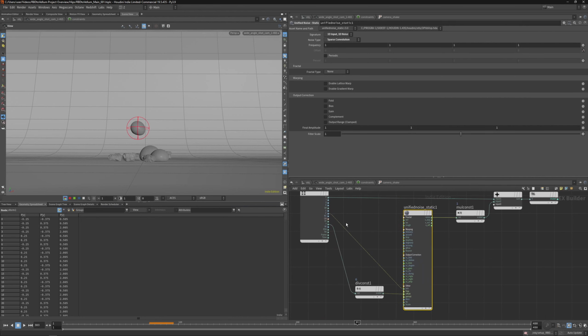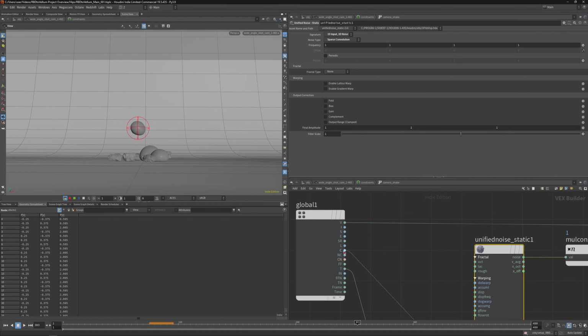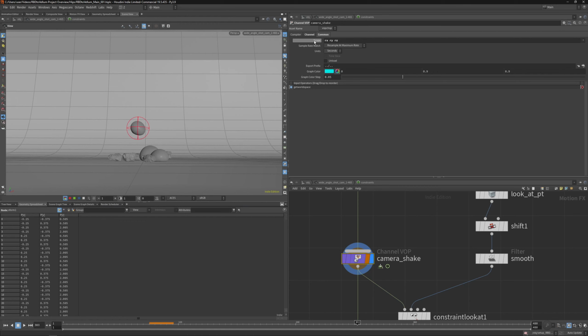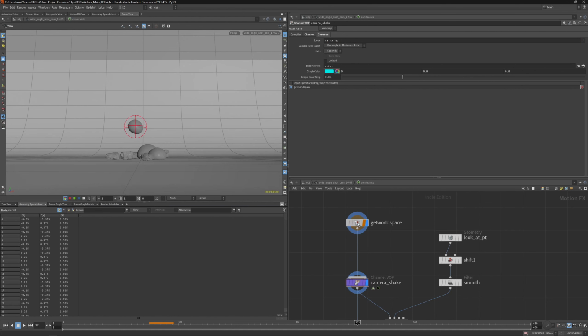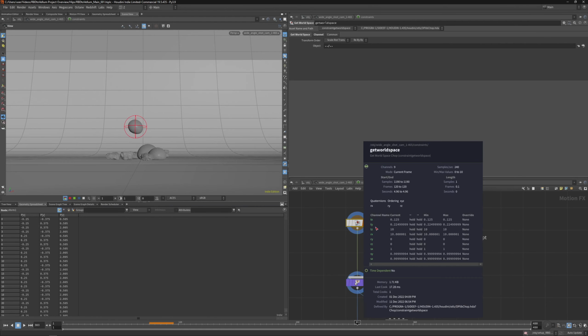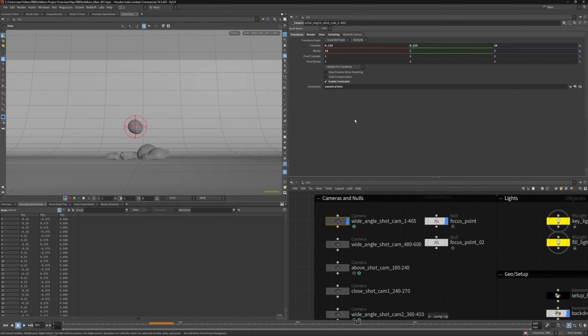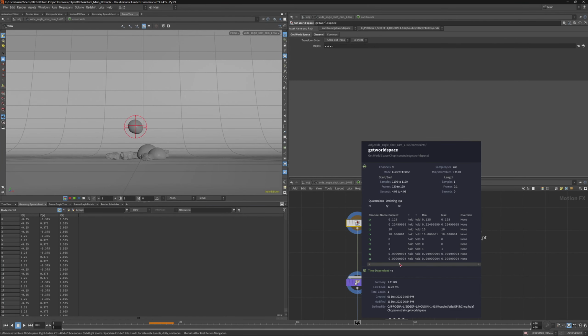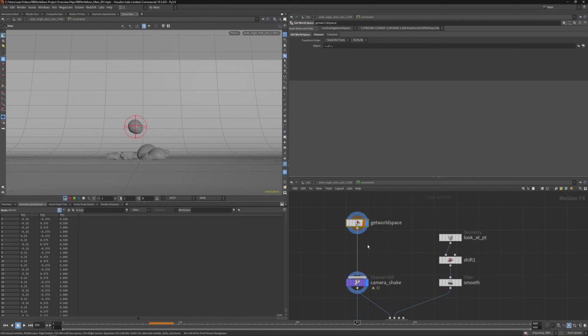As a position input, I'm using this C input here. Basically, this is the channel number of the current channel. So in this channel warp, we are scoping only the rotational axes. With this node, we take in all of our channels, which is translations, rotations, and scaling. In the case of the camera we don't have scale, but it still gets it, because I think internally it still has some scale.